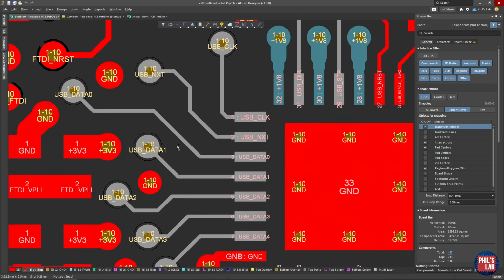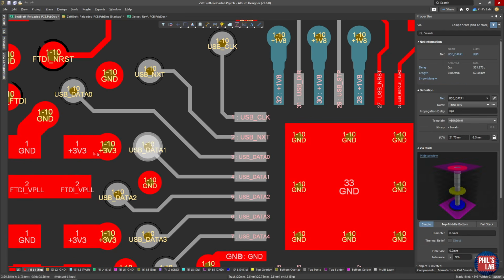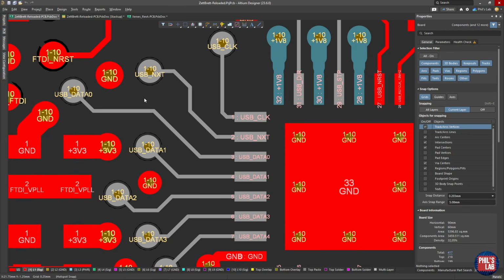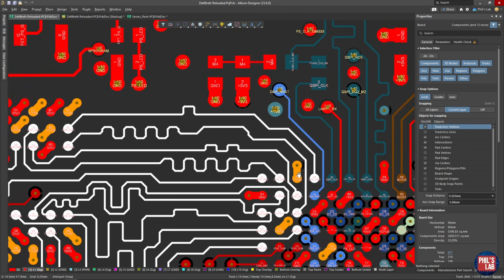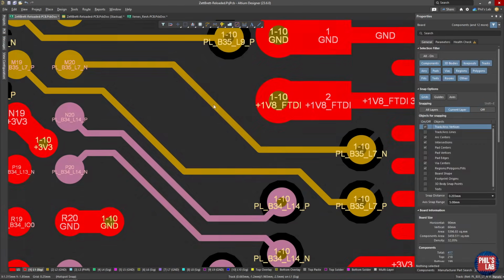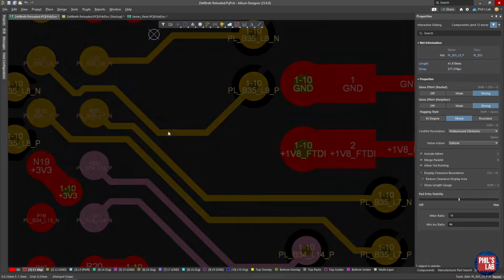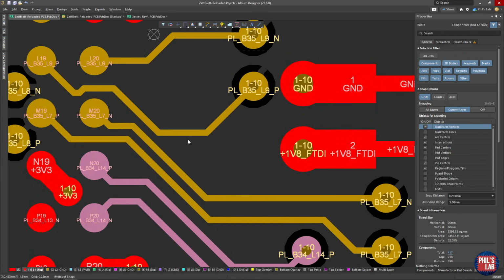Maximize the spacing between features, so that's vias, its pads, its traces as far as you can and as far as is reasonable. And this is true for every bit of routing I do, unless you're very, very space constrained. So maintaining spacing between all traces, pads, vias, and so on as reasonably as you can. Not just, for example, grouping traces as narrow as you can together. This isn't great for the reasons we discussed previously.